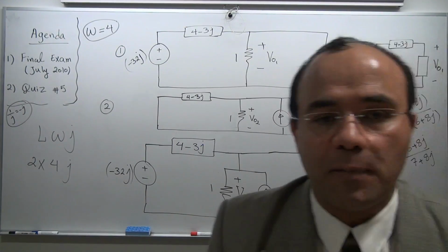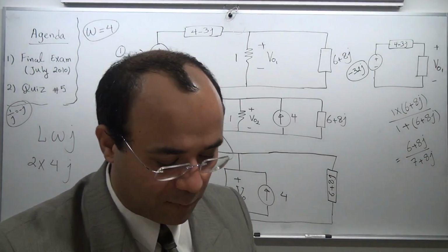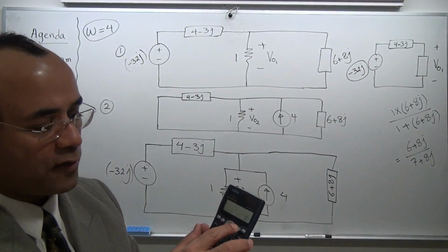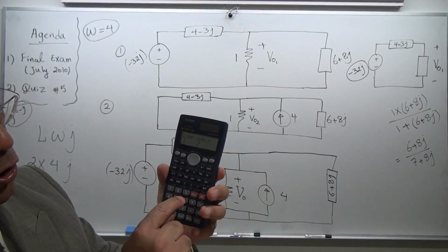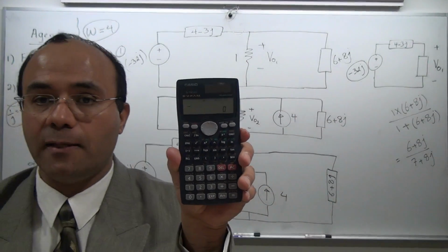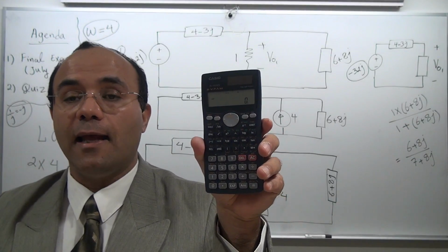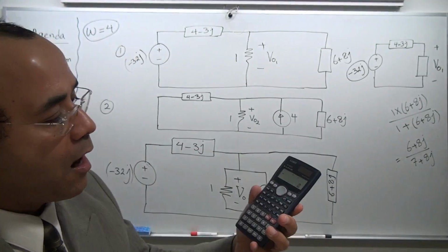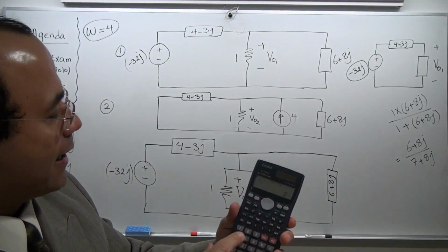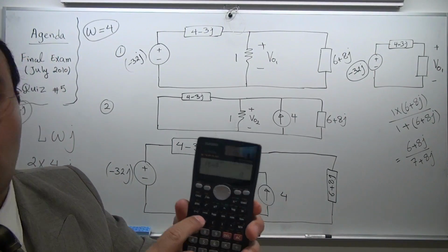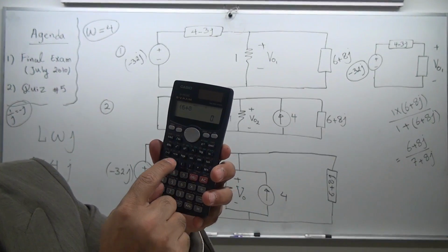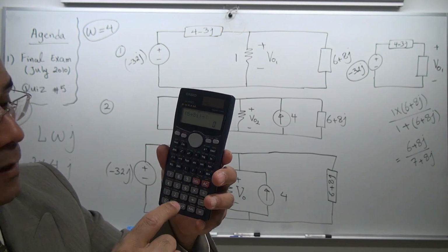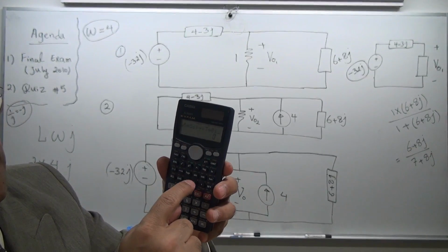As we have shown you before in the calculation, and I hope this might be visible, this is a regular calculator. I'm going to keep a bit of a distance so that everybody knows. I'm going to go into mode. I'm going to push 2. I'm in a complex domain. And one thing you need to keep in mind is whether it is degree or radian. By default, it is in degree mode. So I want to do a division, open bracket, 6 plus 8 times J, close bracket, divided by, open bracket, 7 plus 8J, close bracket.